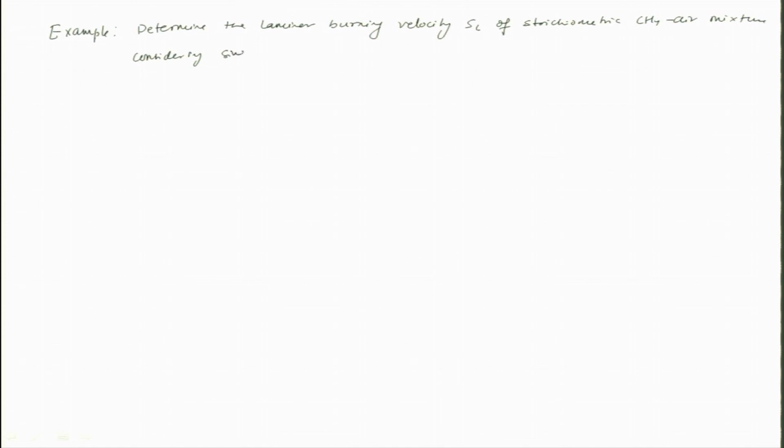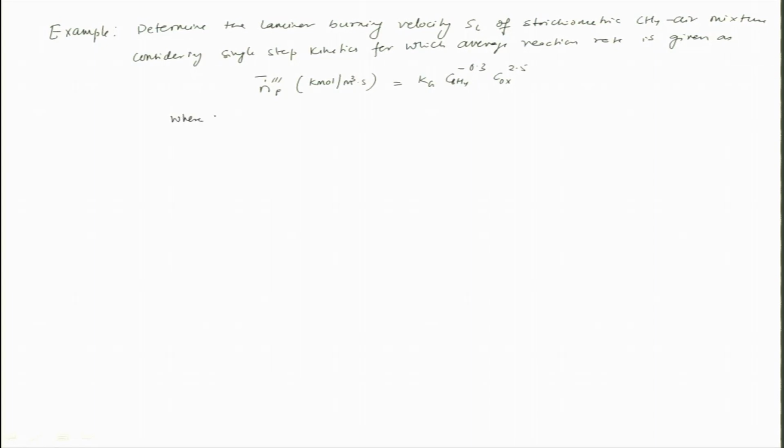considering single step kinetics for which average reaction rate is given as kilomole per meter cube second, right, is equal to kg, with C fuel 0.3 and C oxidizer 2.5, where kg is 1.04 into 10 power 11.